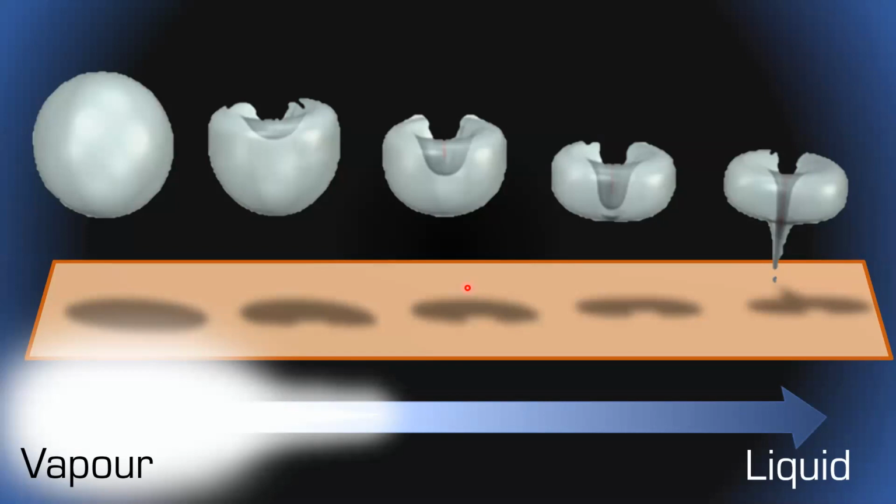Now, it does not do this nice and evenly. It does not collapse on itself evenly to a nice little pop. What happens is it sends down a pressure spike right at the very end of its collapse. And that pressure spike is between 200,000 to 300,000 PSI. Now, I don't know about you, Chris, but I don't know of too many materials that can handle 200,000 to 300,000 PSI. It's pretty aggressive.